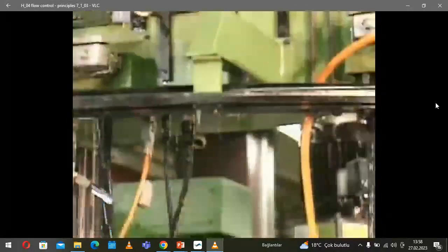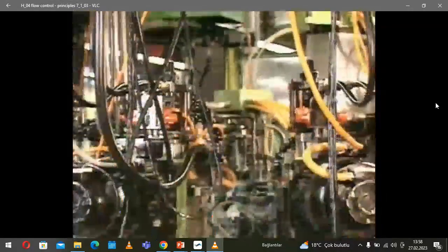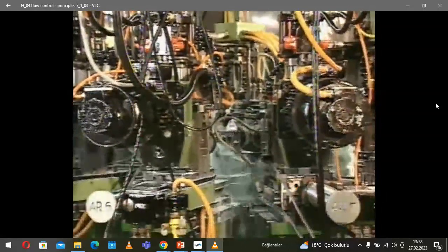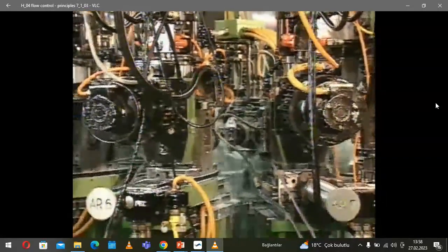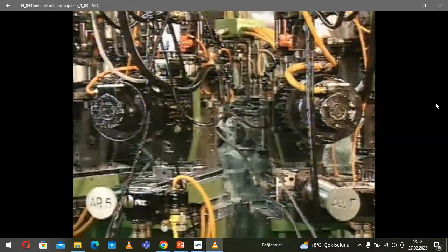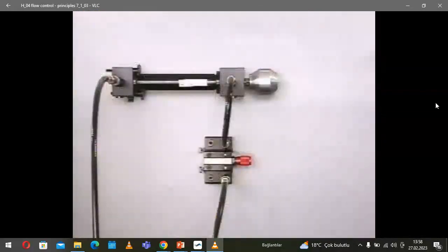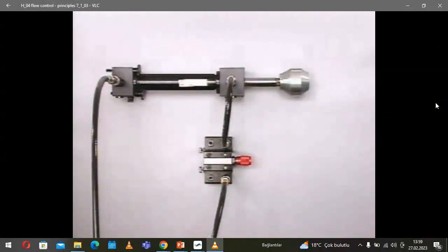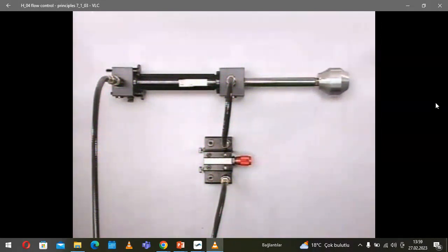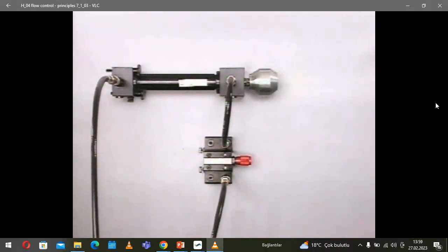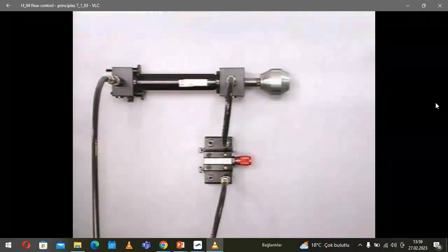In some machines, this isn't important. But this machining complex requires greatest precision, so that any rise in oil temperature is undesirable. So in a case like this, it's better to restrict the flow in the exhaust line. By this, we mean that the flow of oil to the tank is restricted, because it doesn't matter if the oil heats up. At the same time, the cylinder piston is hydraulically clamped, which improves precision.